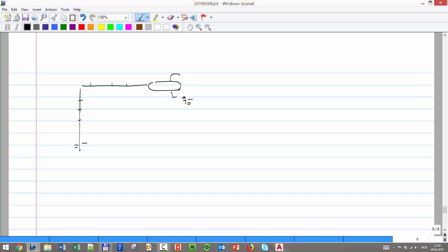For example, if you look at oil, now I'm going to take a small detour again. Here I'm getting some Q oil, some rate of oil. If I go to any place in the system, I'm going to have the same Q oil, like a mass flow. But you're going to get different QO at local conditions. Why? Because maybe the oil here is simply pure oil, with no gas coming out of solution.